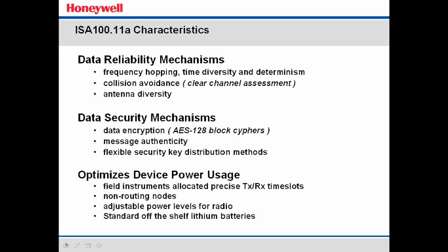Wireless is a shared medium, meaning the air is the air. Whatever RF device is powered up, you're all sharing the same space. So what this system does is it has what's called clear channel assessment. When it boots up for the first time, it more or less sniffs the air, decides what's out there, if anything, and it goes to a part of the frequency band that's least congested. If it sees something at the top of the band, it'll choose to operate at the bottom of the band, so as not to cause interference or be interfered with.